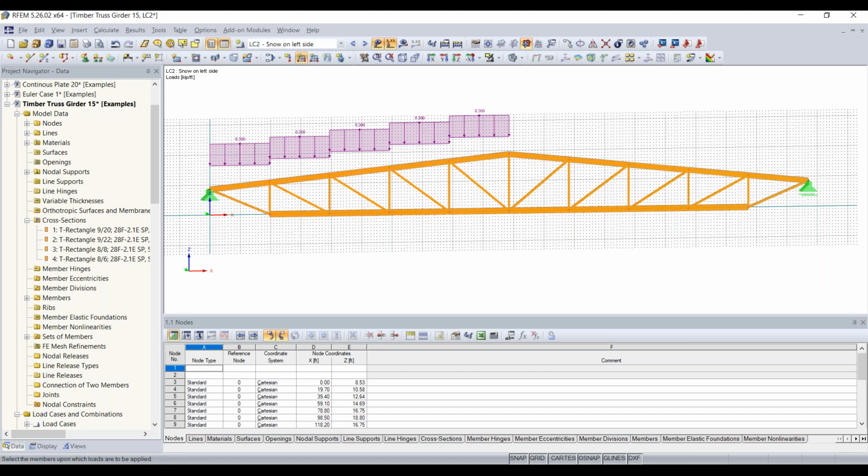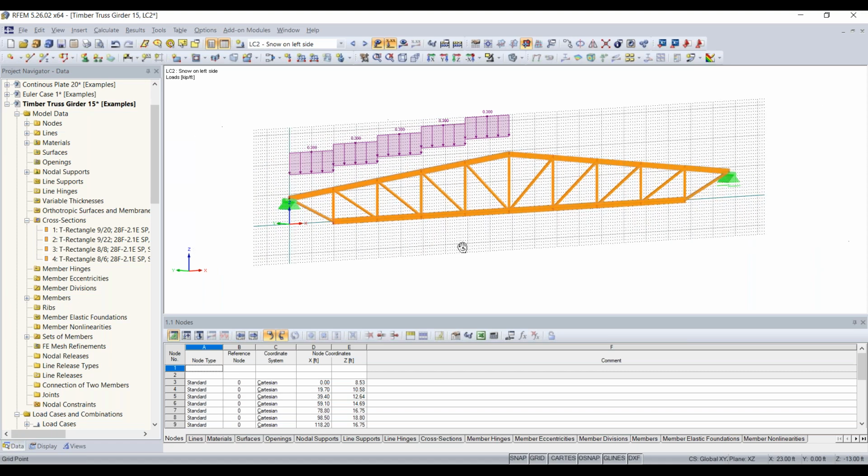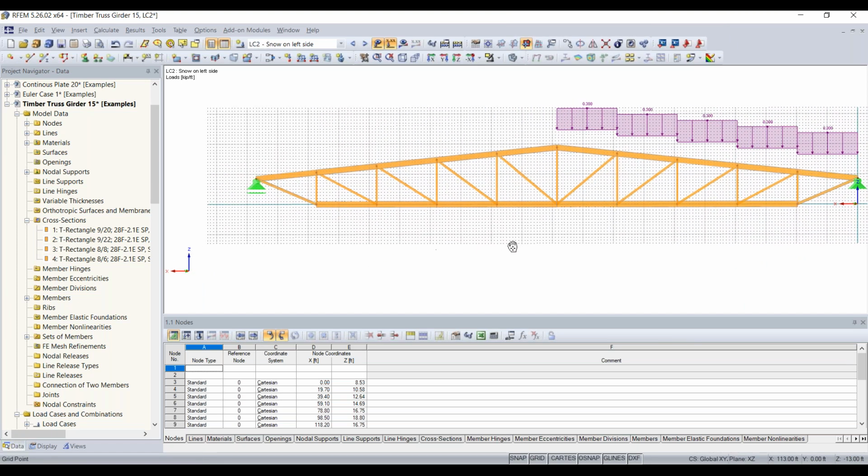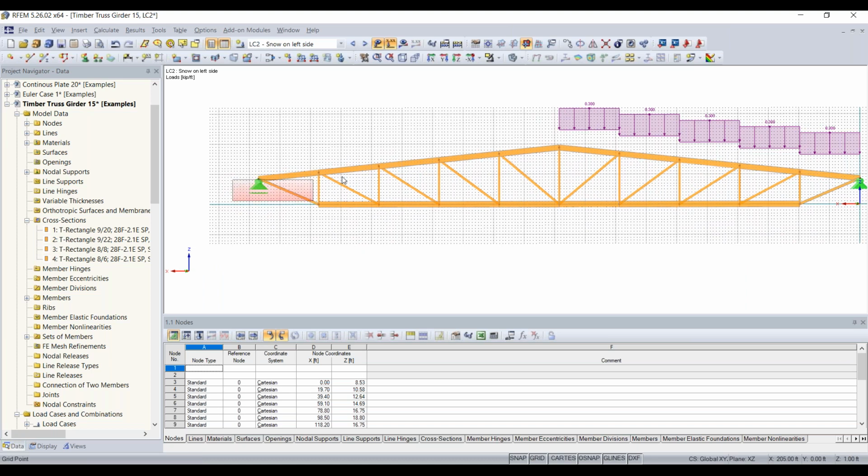You can see that it's the projected member length, taking into account how snow will act on our roof there. So we'll right click, and now we want to do the same thing for the right-hand side. I'm going to rotate my model, highlight again, selecting only the beams up here, and then choose new member load.